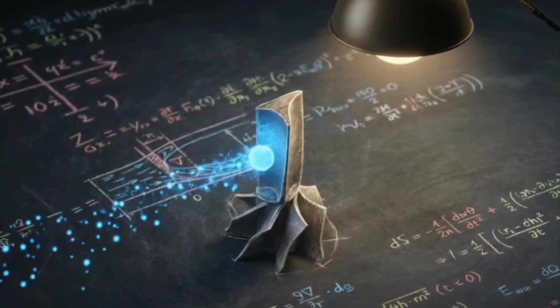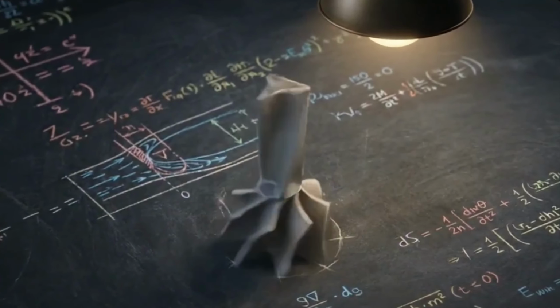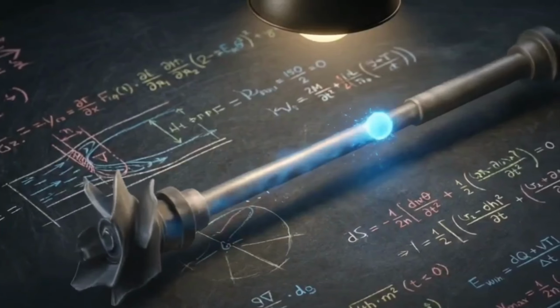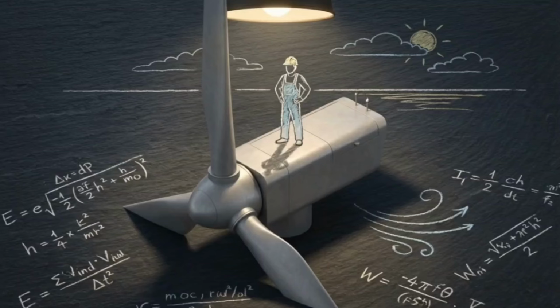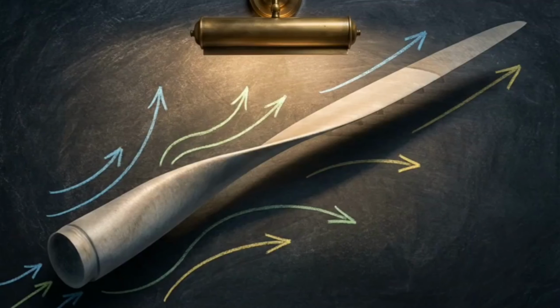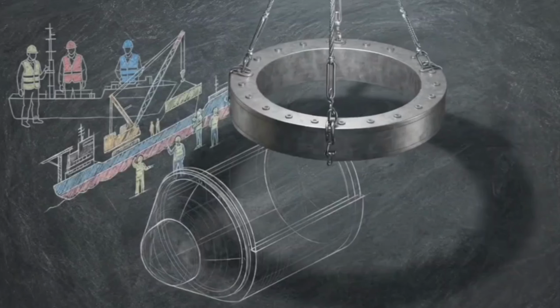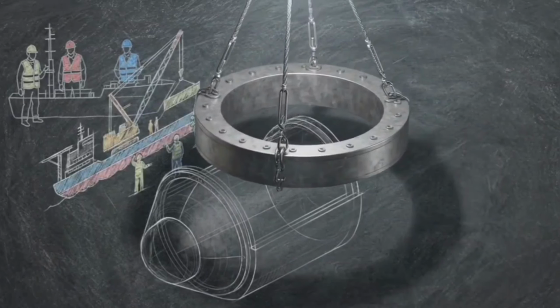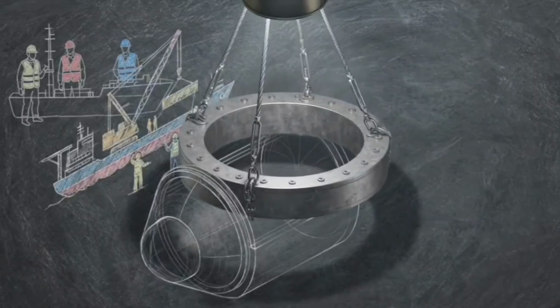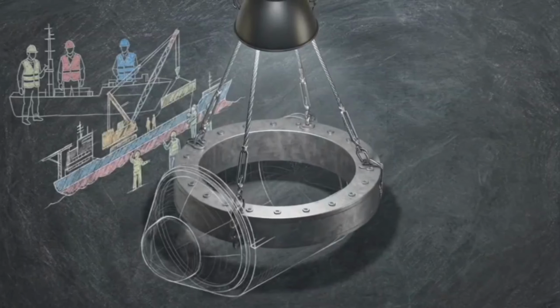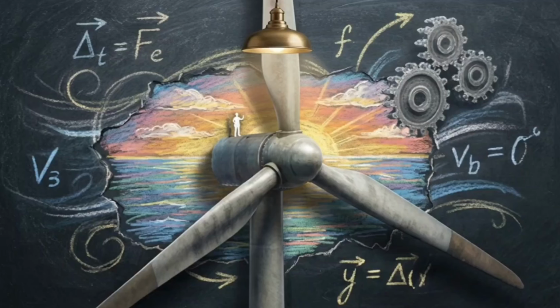Pulling back, we can trace the complete, uninterrupted pathway of energy transfer. The entire energy chain operates beneath the absolute fluid dynamic ceiling of Betz's law. Aerodynamic capture extracts power using highly precise blade twist and lift vectors. The internal drivetrain translates that heavy physical torque into precise electrical grid synchronization. All future advancements in wind energy, from lighter composite materials increasing sweep areas to massive direct drive generators, are compounding engineering strategies. They are all designed to inch a fraction of a percent closer to an unyielding theoretical law of physics.